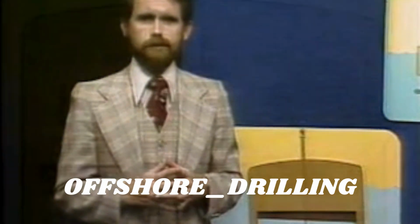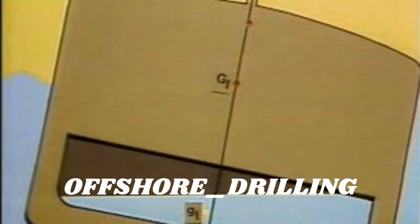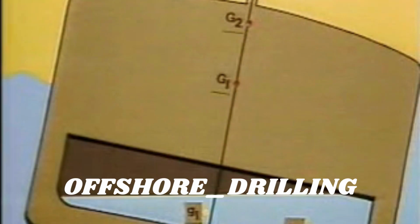Let's take a look. Here we have a vessel in an upright position where the center of gravity is indicated by a capital letter G. We have a partially filled tank, and the center of gravity of the liquid in this tank is indicated by little g. When the vessel is inclined, the center of gravity of the liquid will shift to little g2. For reasons that are beyond the scope of this discussion, the net effect of this movement of little g upon the vessel's stability is an apparent movement of the center of gravity of the entire vessel, or G1, to the higher location of G2, shown here.